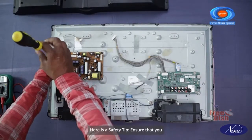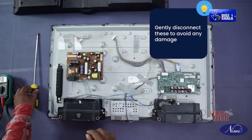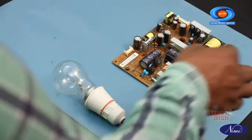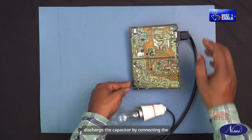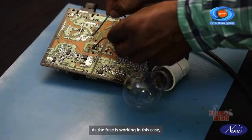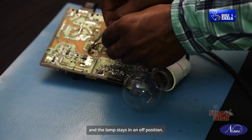Here is a safety tip. Ensure that you gently disconnect these to avoid any damage. Handle the board cautiously due to the fully charged capacitor. Use a discharging tool to safely discharge the capacitor by connecting the cables from the discharging lamp carefully. As the fuse is working in this case, the capacitor won't charge and the lamp stays in an off position.